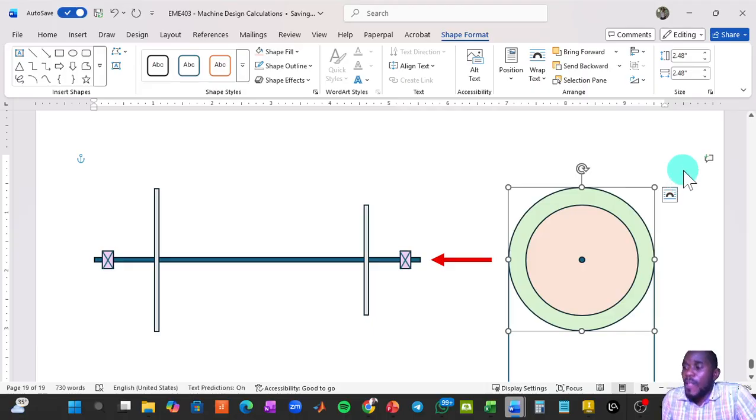There we go. So you see me being keen to show, because if you are looking at this arrangement from the right hand side as designated by this arrow, then you would see the end of this shaft. I've deliberately not drawn the bearing, otherwise we'd have seen another circle there that represented the bearing. And then we will see this pulley, and we will now see the outer part of this second pulley, because the second pulley is behind this first one if I'm looking at them from this direction. That's what you can see here.